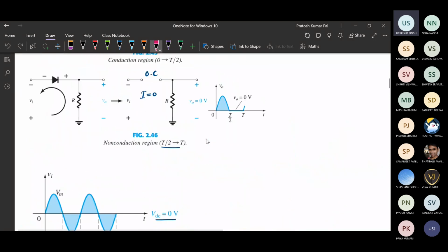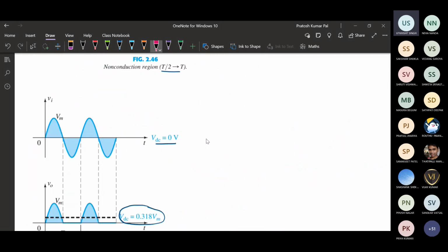In the ideal case, the output frequency will be the same as the input frequency, and the conduction angle we can represent by Ca. The conduction angle phi here is conducting only from 0 to pi. A sinusoidal waveform is periodic for 2 pi, so from 0 to pi, that means half of the time period, the diode is turned on. So the conduction angle will be pi.